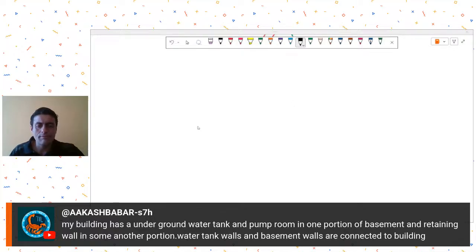So for them, the modifier is not very clearly given in the code. Maybe you could use the modifiers for slabs, because the slabs are also for out of plane moments. So maybe you can use the slab modifiers in such cases.